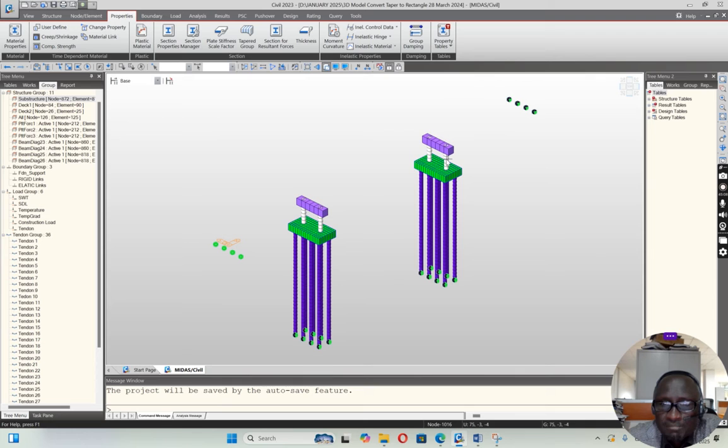So if I wanted to make sure this pier support and the pier cap were supposed to be construction stage 2, I would now do substructure 1 piles up to pile cap. Then number 2, I would do pier support and pier cap. Then I move to deck system. That's what I would do. But here I decided to make it all the way here, so that it's not going to make a lot of changes. So now that is what I will do, and then I can take it back.